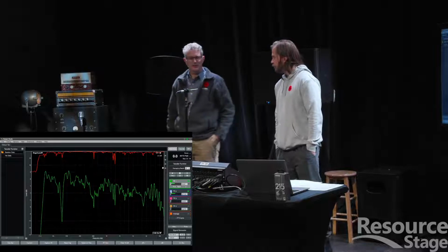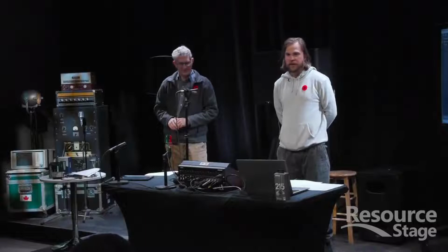One of the things we wanted to mention as well: Paul was doing the demonstration of the crossover with the mixing console. Normally, in all circumstances, we would not use a mixing console for this. We would use a separate digital signal processor to look after that crossover region, equalization, and optimizing the loudspeakers for the room, for the space. Then the mixer can do what it does best, and that is mixing audio signals. The processor looks after the crossover, and people don't touch that. The main benefit is that if you did your crossover on the mixer like this, you could derail the whole tuning of the system with one button. That's right. Which we want to avoid.